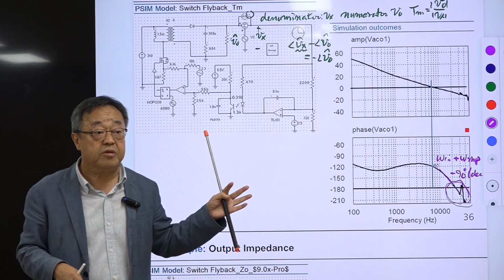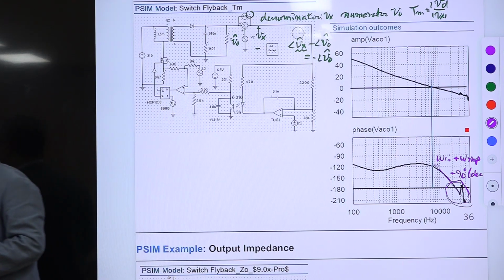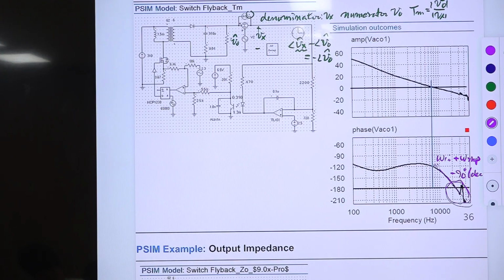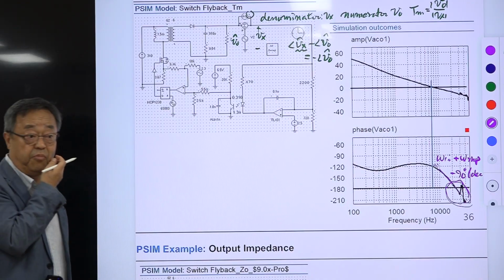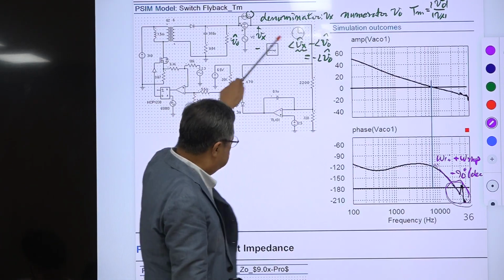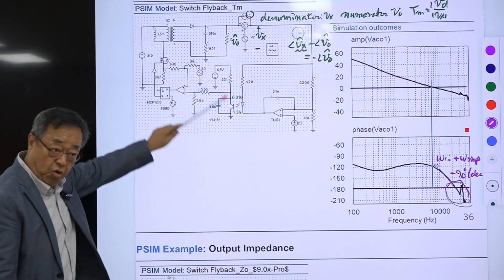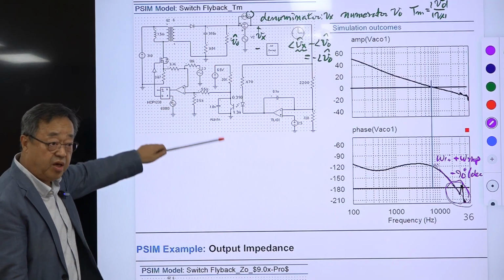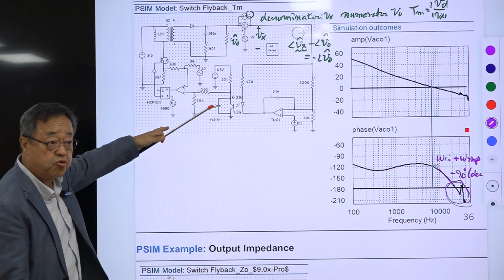So this is good. In the design steps, we use the analytical results, transfer functions and everything. In the past, people simulated everything using the small signal model, which is very cumbersome, and this is very simple, but you should know what you are doing and the implication of the result of your simulation.